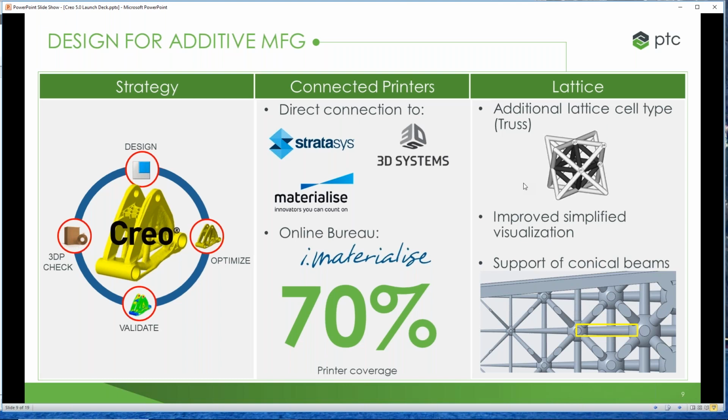So talking about metal printing a little bit, that is a new extension for being able to do that. Metal printing is a little bit different than polymer printing as far as the support structure, and that's kind of what we see in the middle image here with the yellow supports. Now, in the polymer world, in the plastic world, the supports basically just hold up the part, right? That's what they do. But when we're working with metal, there are actually things that we have to take into account, like temperatures and things like that, heuristics. And what we need to be able to do is control these supports a little bit differently than we would with your typical kind of plastic printer.